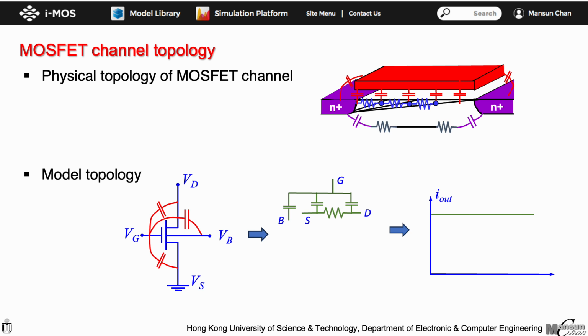As a compromise, some models may use the lump circuit models for DC and transient simulation, but switch to the distributed network when performing AC simulation. This solves the problem by providing additional accuracy required by frequency domain simulation, but it causes some concern to the model developers as the frequency domain model is no longer consistent with the DC and transient simulation model.